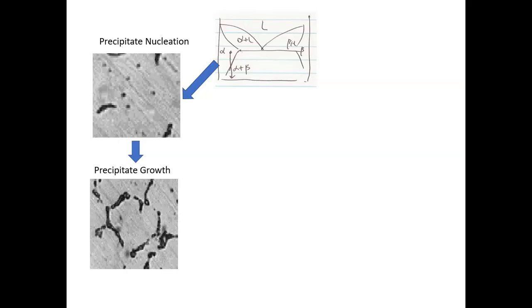But there's another pathway. In order for this to occur, diffusion in the solid state usually occurs very slowly, right? So this is a very nice process, and it's controllable in most cases. If you want a reasonable size of grains, you want to control how much of the beta phase you produce, you can use the TTT diagram, which we derived a couple of lectures before. So you have very nice control of all these processes. But the problem is that you have to be patient. You have to wait for the diffusion to occur slowly and control the temperature, etc. But this is one useful pathway.